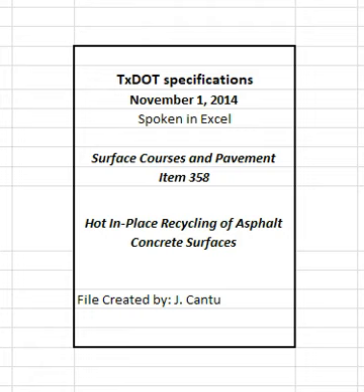4.6 Placement of recycled material. Spread the material using a paver and screed attached to the mixing/milling unit or a traditional paver in a separate and continuous operation meeting the requirements of Section 320.2.3.1, Asphalt paver. Spread the recycled material to the established lines and grades. Ensure the temperature of the recycled material behind the paver is greater than 200 degrees Fahrenheit.